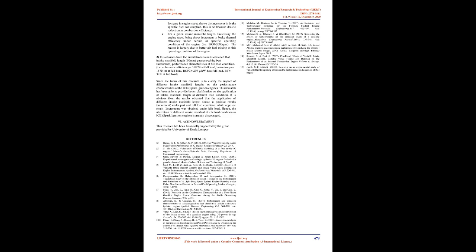It is obvious from the results obtained that the application of different intake manifold lengths shows a positive result, an increment, under part and full load condition, while the opposite result, a decrement, was obtained under idle load. Hence, the utilization of different intake manifolds at idle load condition in ICE spark ignition engines is greatly discouraged.